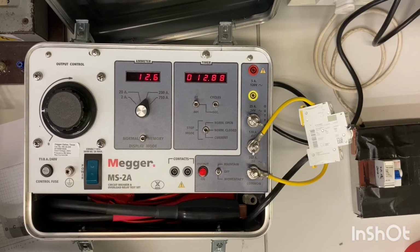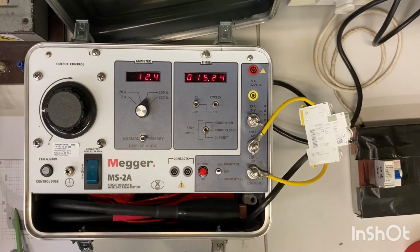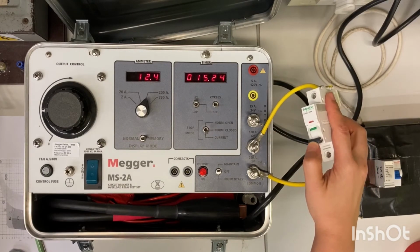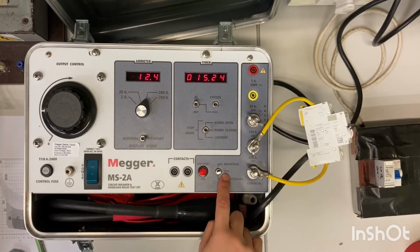And after that, we have to wait until the MCB trips. So we just heard the click sound and the MCB has been tripped. So once again, back to off position, and we have to record down the data and wait for 1 minute. After the MCB is cooled down, we can try a larger current value.